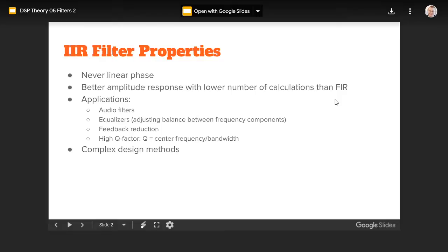So if we add the poles like that, we have actually added only 4 poles instead of 8 zeros. And that will do the same thing, but with gain, a flat response on the passband. Okay, so it's a more cost efficient way of getting the passband flatness.